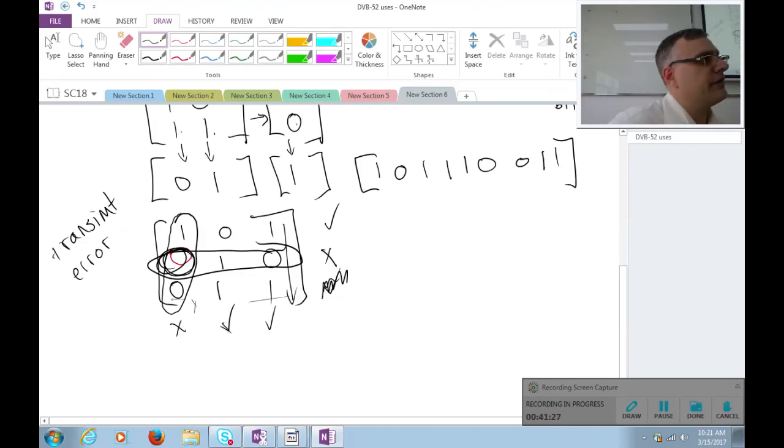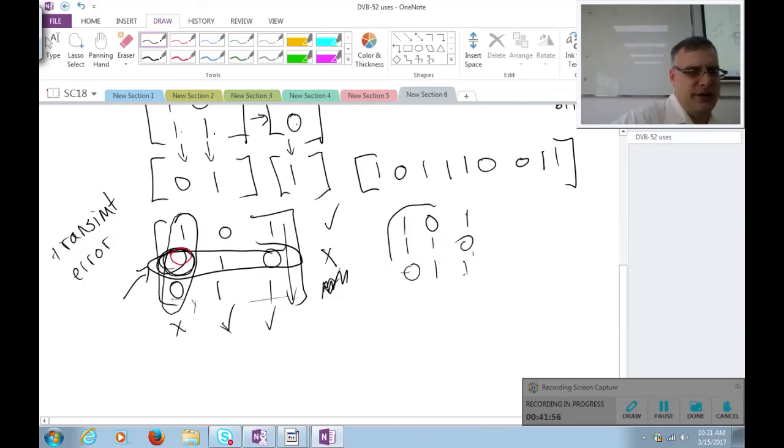So you can think of a product code like this as simply a giant game of binary Sudoku, right? You ever play that game where you try to figure out what are the missing numbers? It's the same thing. What are the bits that are in error? So when I receive the signal, I know that I just need to flip whatever bit that is, and I can recover the original data stream. I'll use these bits to figure out the parity. I'll flip the bit, and there I've recovered my original data.